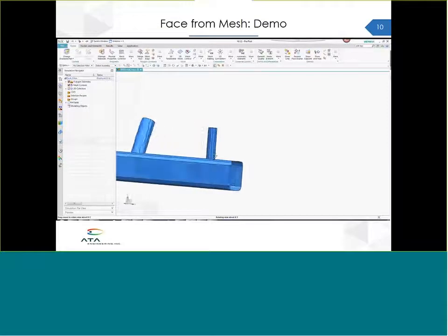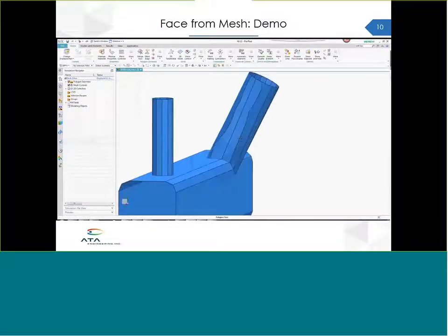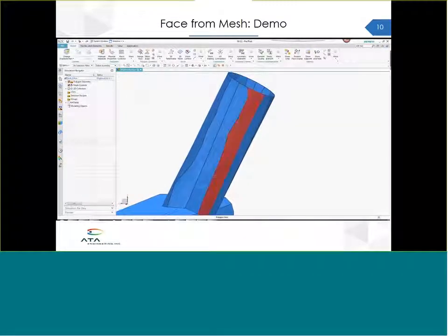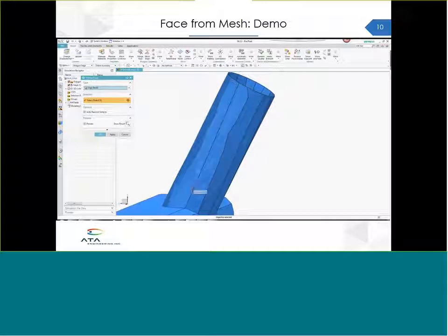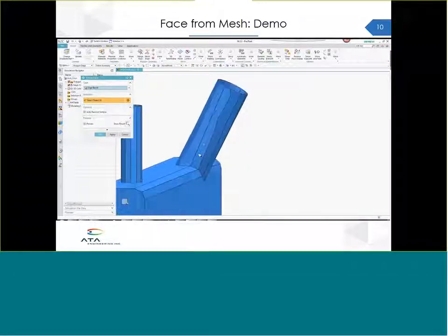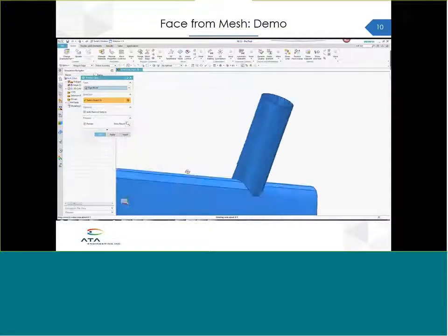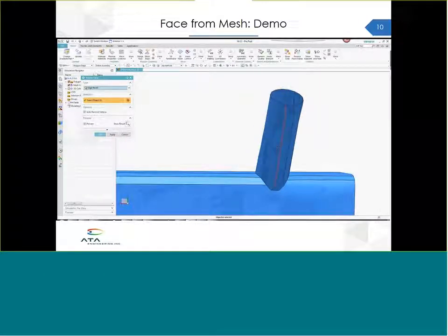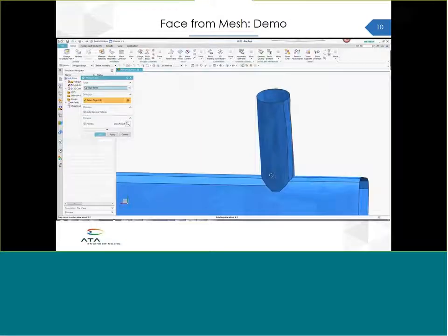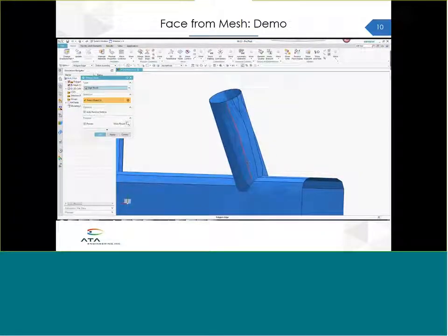You can also easily remove any unwanted polygon edges using the merge face command, which has existed in NX and Simcenter for quite a long time. So we can easily delete most of these unwanted polygon edges. You can even obviously keep in some useful polygon edges if you think it's going to help the mesher be able to more appropriately mesh your polygon body.